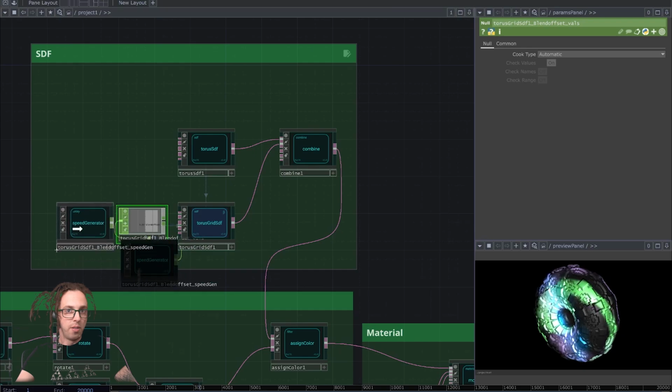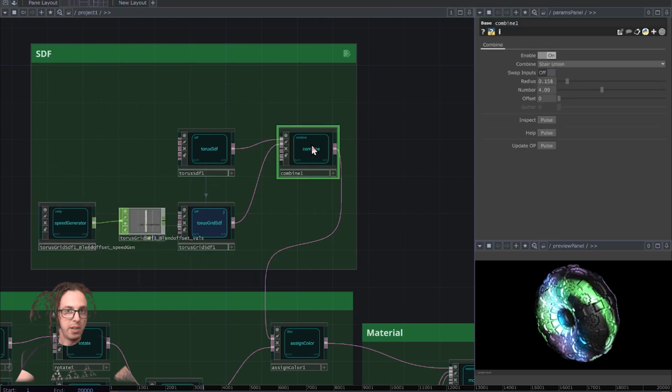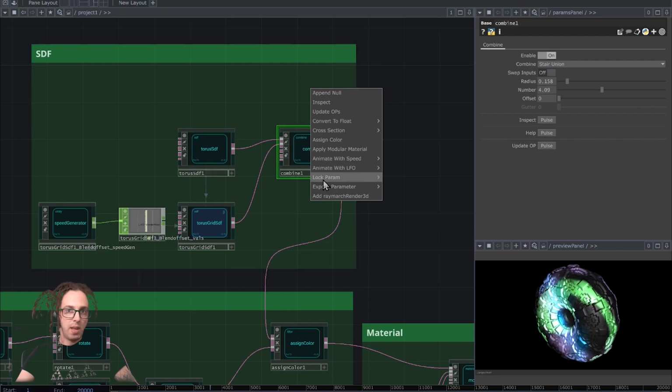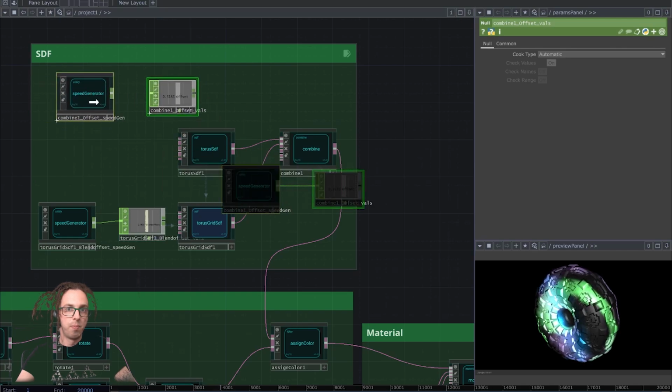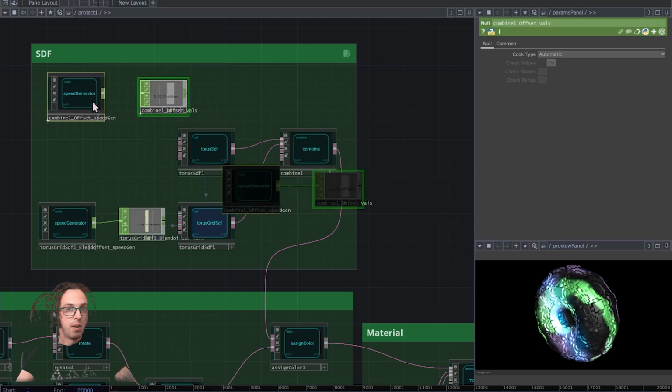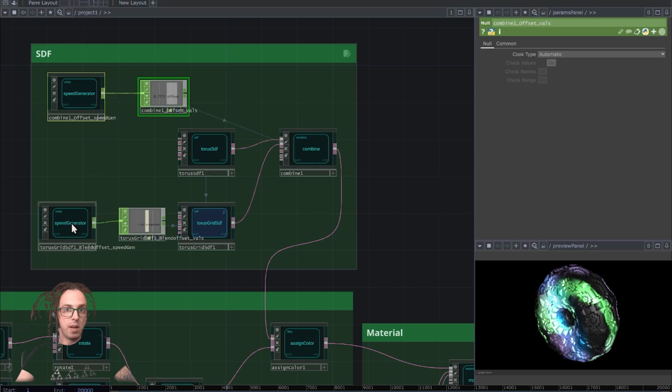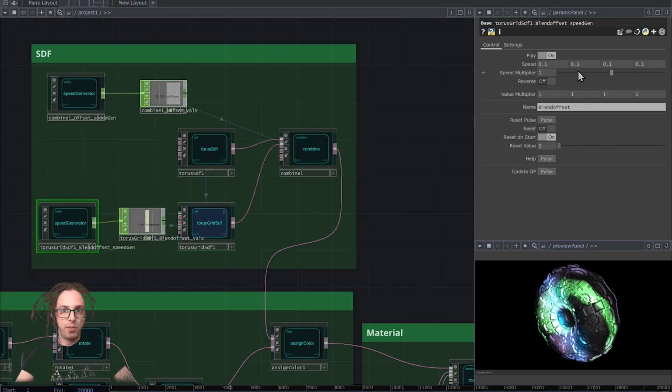And then for the Combine, we're going to do a similar thing. Select that, Alt-Shift-R, and under Animated Speed, choose Offset. Then you can try different combinations of speeds there, or maybe reverse one of them. You can get some really cool looks by varying those to different settings, but you can refine that later.